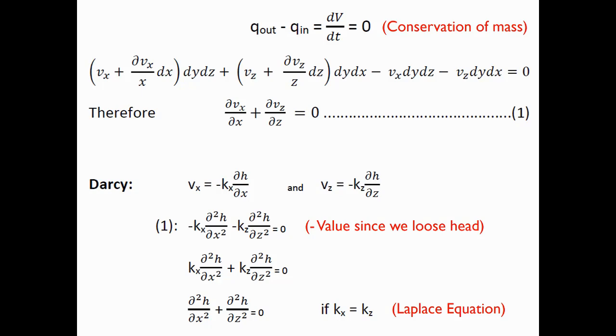We're not gaining head, of course, because the flow is impeded. And then Laplace came with an equation which basically says that the permeability coefficient in the X and the Z direction is similar or the same. And so the Laplace equation basically describes how the energy of a fluid changes as it flows and is independent of the actual permeability. And the Laplace equation is actually used in many other disciplines, not only in this particular case.